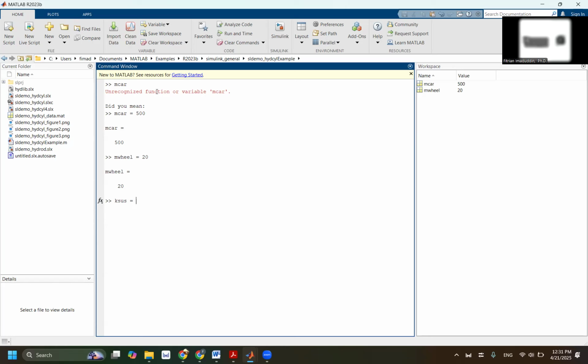So what is K? K equals the force over the deflection. Yeah, so the force is 250 over 0.01. 1 centimeter, not 10 centimeters. So 250... 25,000 Newton. So 25 kilonewton.